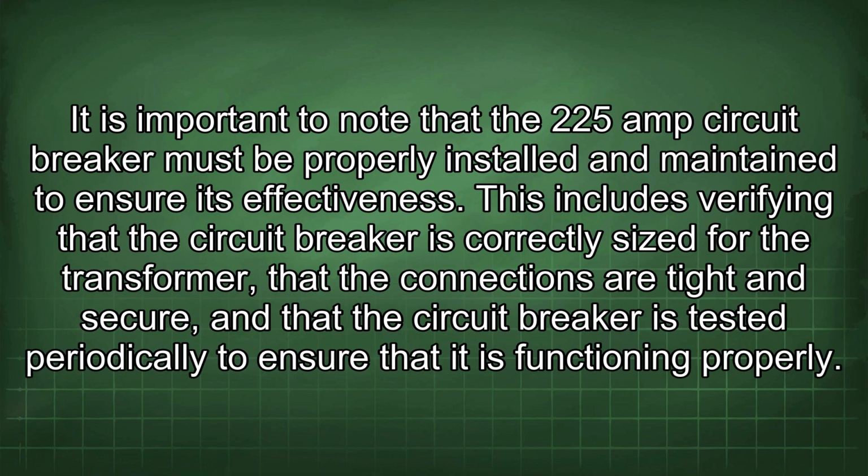It is important to note that the 225 amp circuit breaker must be properly installed and maintained to ensure its effectiveness. This includes verifying that the circuit breaker is correctly sized for the transformer, that the connections are tight and secure, and that the circuit breaker is tested periodically to ensure that it is functioning properly.